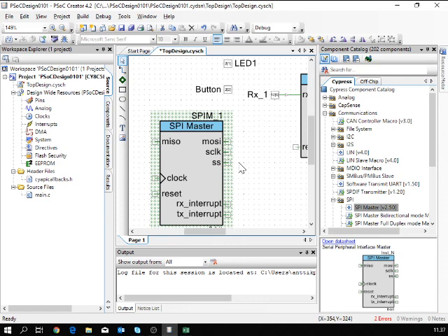You would need that pin, of course. Clock: read the datasheet and see how fast your clock can be. That device, you can use it up to, was it 1 mega samples per second? So you can have a 60 megahertz clock there. But check the datasheet, don't believe me. I make mistakes. I don't recognize those myself, though, but somebody has told me that I have made a mistake once. Okay.